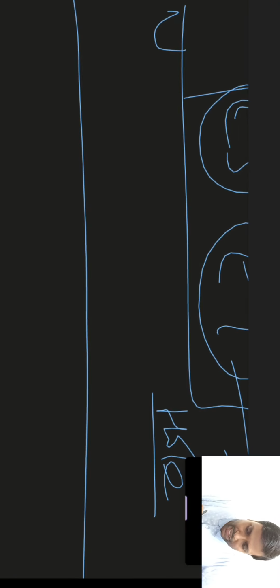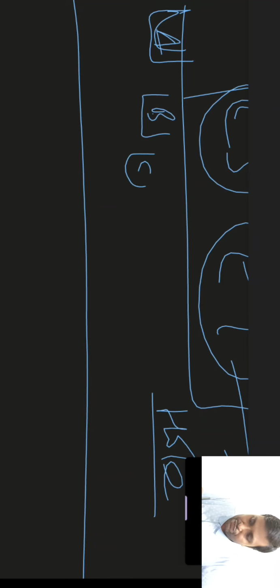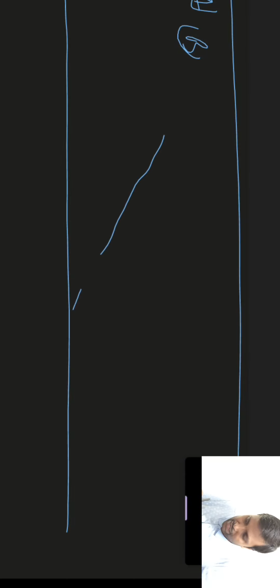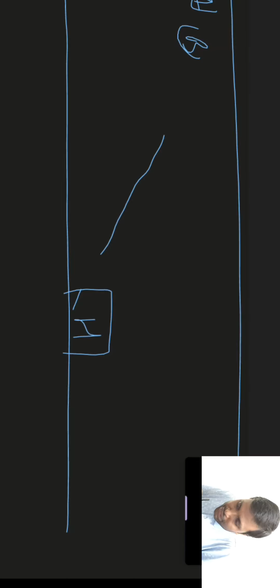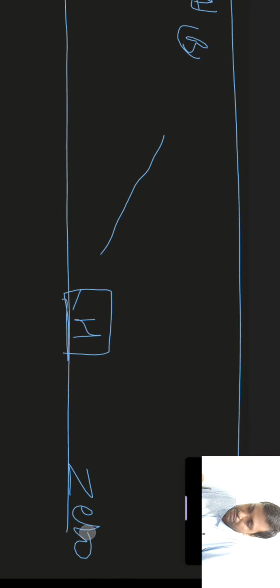We are starting from A, we are then going to B, then C. After C, suppose I am again drawing this diagram, there has been some mistake, and let this be A, this be B, and same we will move further, and here will be H. H is the fundamental deviation for hole whose lower deviation is 0, that is it matches with the zero line.